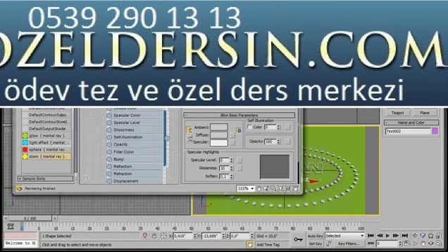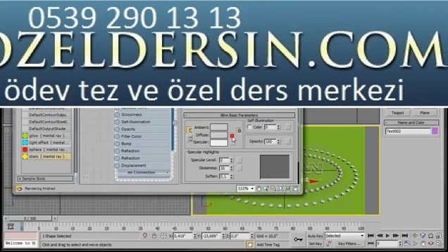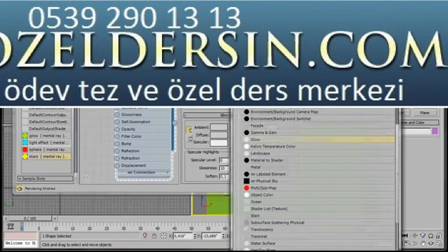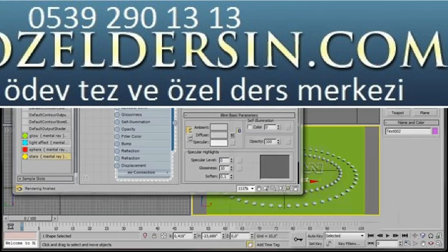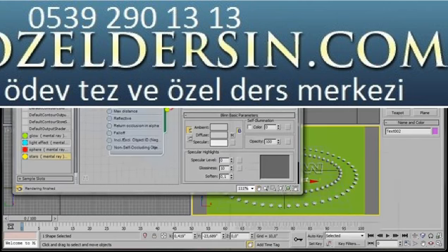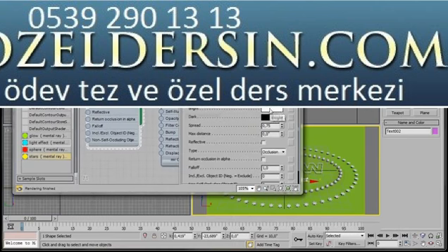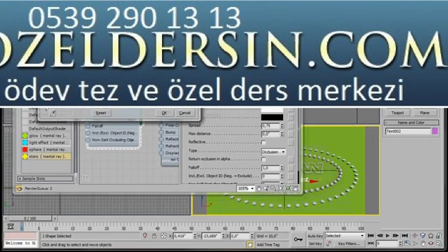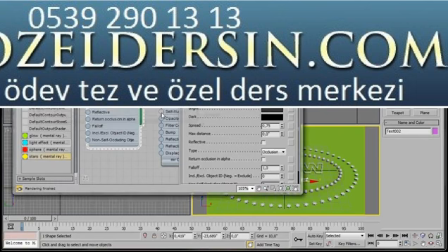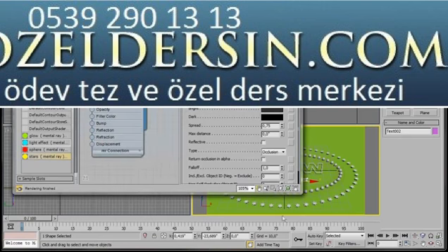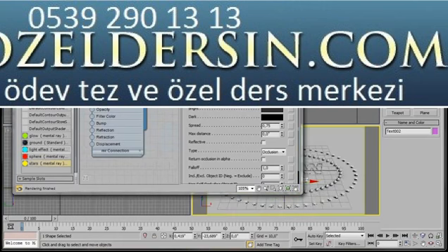Let's go over to the small map icon beside the word diffuse. Let's select the mental ray map and ambient occlusion. Double click to open it. And in bright, we'll click on the small color slot, and we're going to bring the dial up to a very dark grey, then press OK to close it. Now we can drag the material over to the plane. Now we can close the material editor.